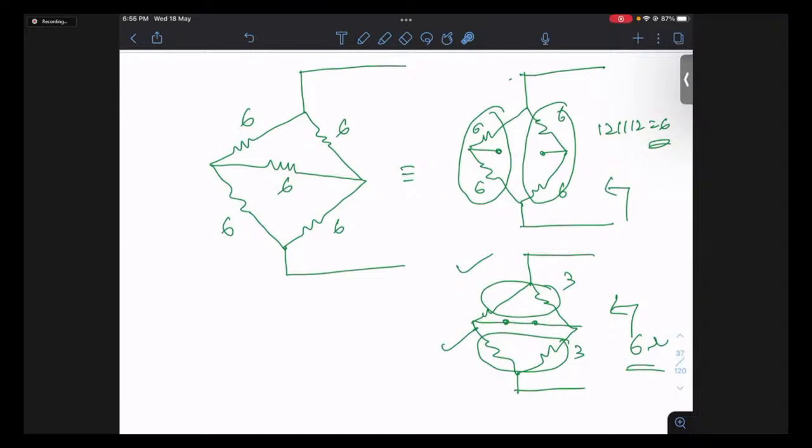But the next point is, how do you know which are equipotential points in a circuit? This is basically some common sense. Assume that some amount of current is coming to this node. There are 2 paths, and these paths are identical with respect to the resistor values.